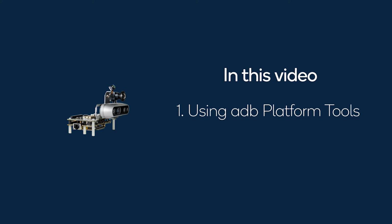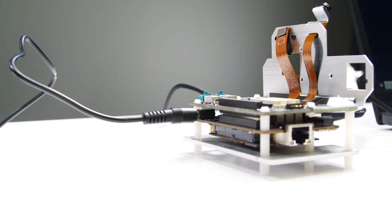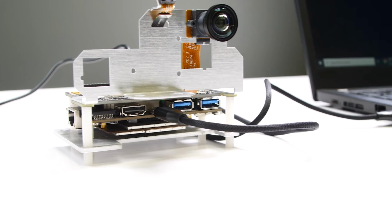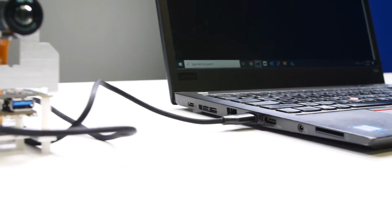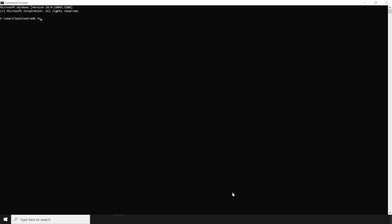Let's now take a look at the ROS installation steps at a high level. Once the DevKit is powered on, connect a USB-C cable between the DevKit and the host PC and enter the commands as seen here to log in as the root, remount the file system with the read-write access, and access the DevKit shell.